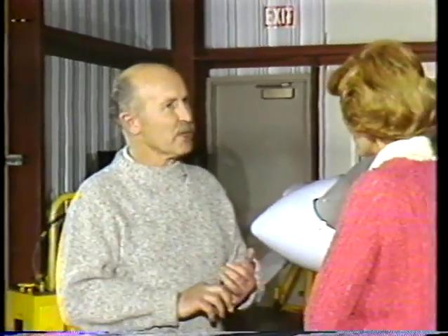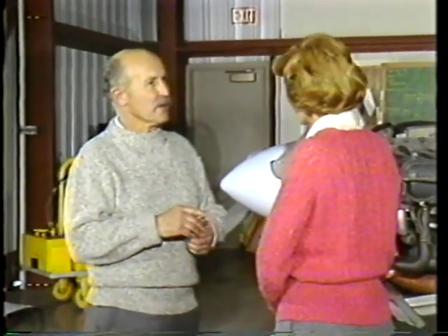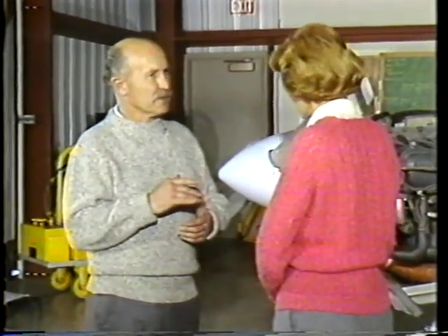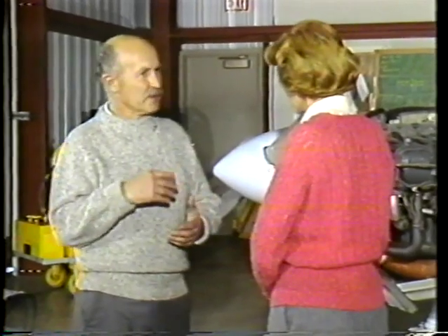Ken, for those who are not familiar with the four-stroke reciprocating engine, can you tell us briefly how it operates? Yes, it's very similar to your automobile engine. In the four-stroke engine, the pistons are connected to the crankshaft through the connecting rods, and as the pistons move down in the cylinders, this provides the rotating motion that drives the propeller. We have our four basic strokes: the intake stroke, the compression stroke, the power stroke, and then the exhaust stroke. And of course, these repeat very rapidly in sequence.